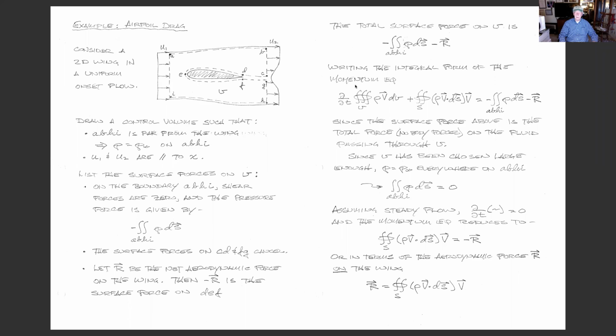It's the same reason that tires on little cars don't wear out as fast as on big cars. One other quick aside, and then I'll shut up, is the LA Times had a thing about people like to pick on SUVs and the big trucks, and they're tearing up the roads. They should be taxed for putting so big a load on a road. Well, it turns out a road bicycle is, in principle, harder on the roads. One that's got 110 pounds of air in its tires, so you can go fast. The load on the surface is exactly equal to the tire pressure.